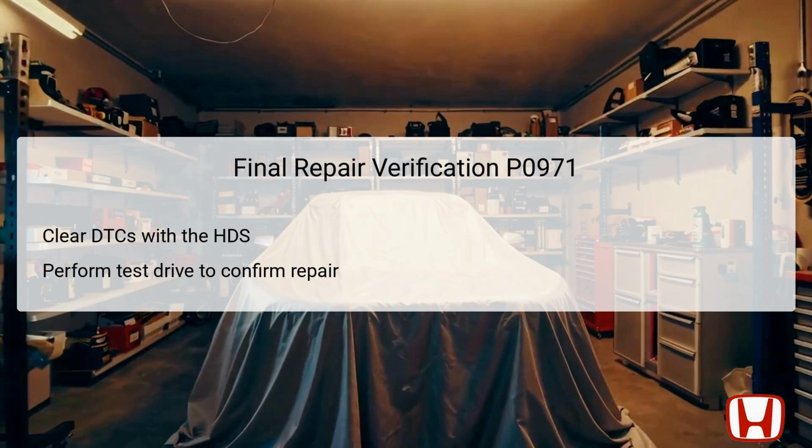Final repair verification is a crucial step to ensure that the issues regarding DTC P0971 have been successfully resolved. After any repairs or replacements have been made, the next step is to clear the DTCs using the Honda Diagnostic System. This action resets the TCM's memory and removes any stored fault codes.